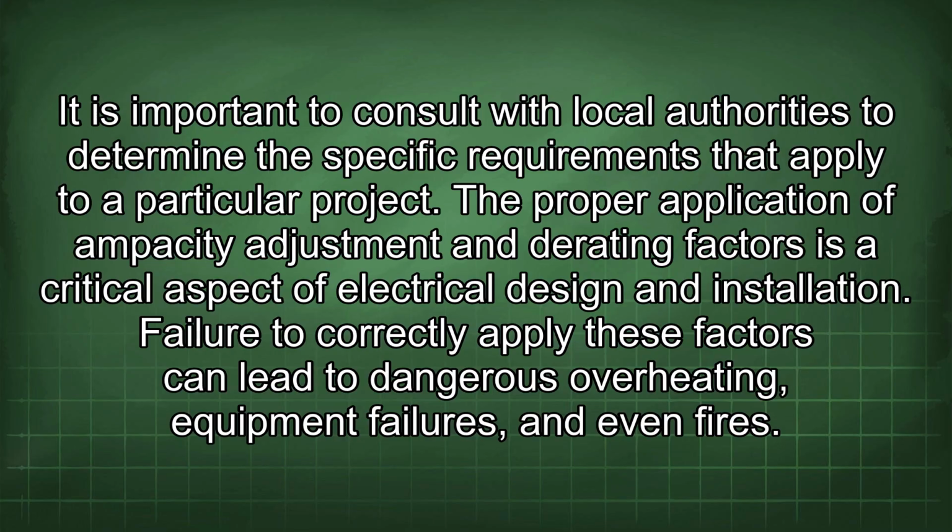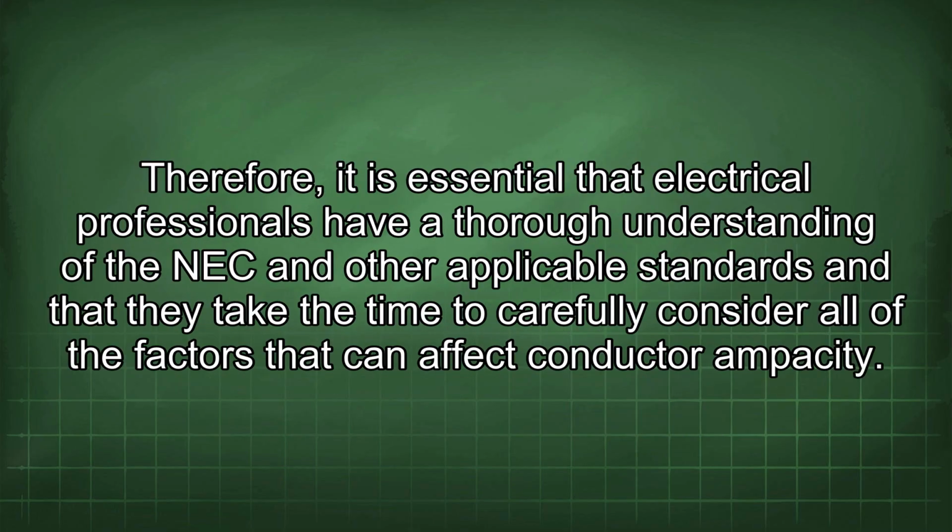a particular project. The proper application of ampacity adjustment and derating factors is a critical aspect of electrical design and installation. Failure to correctly apply these factors can lead to dangerous overheating, equipment failures, and even fires. Therefore, it is essential that electrical professionals have a thorough understanding of the NEC and other applicable standards, and that they take the time to carefully consider all of the factors that can affect conductor ampacity.